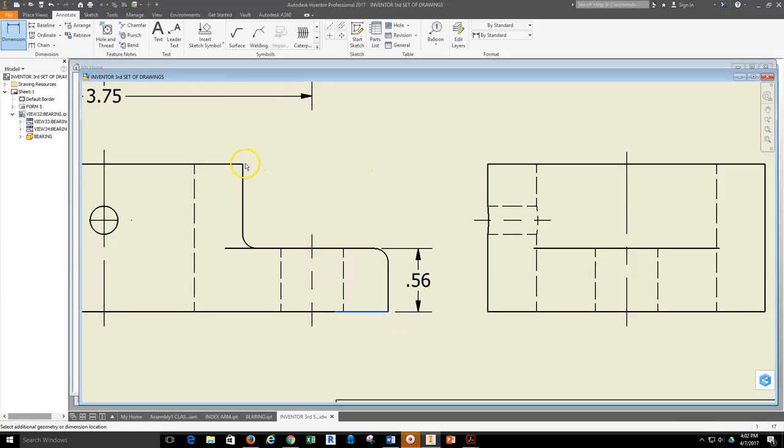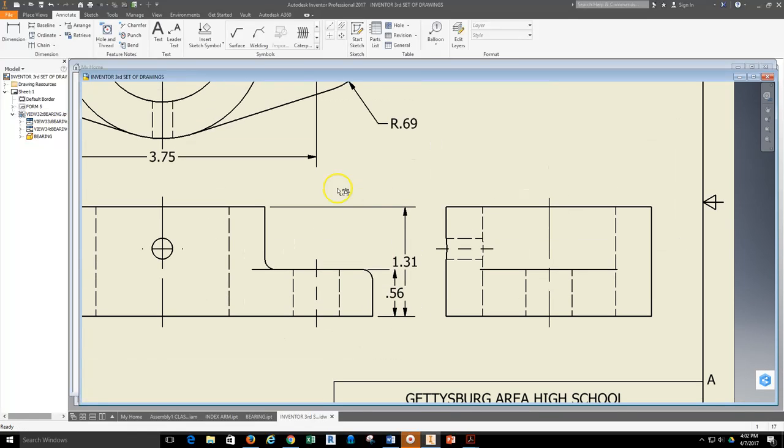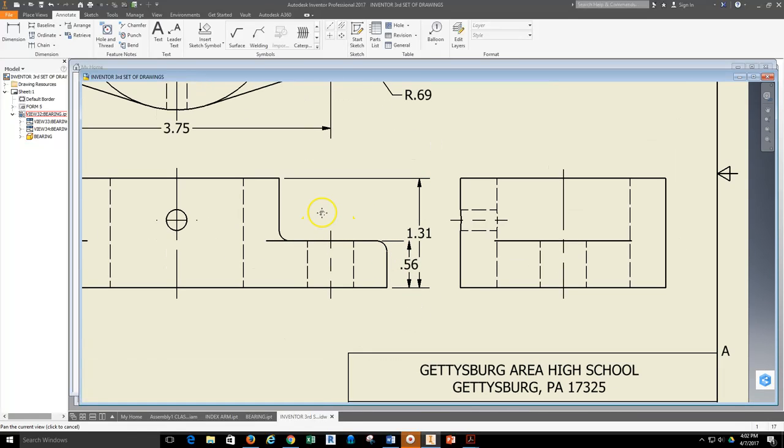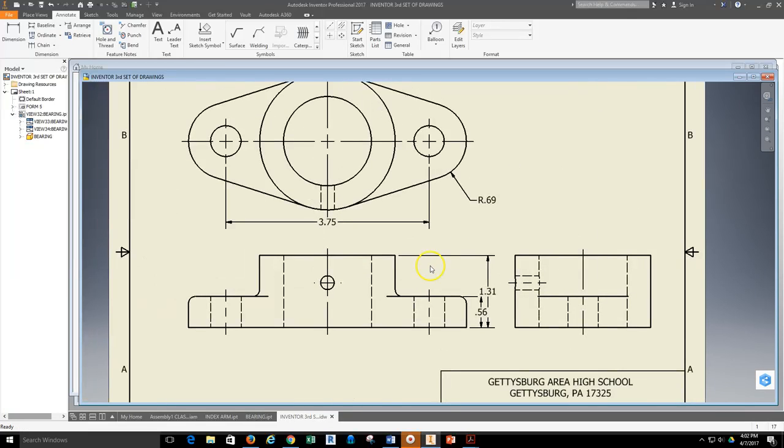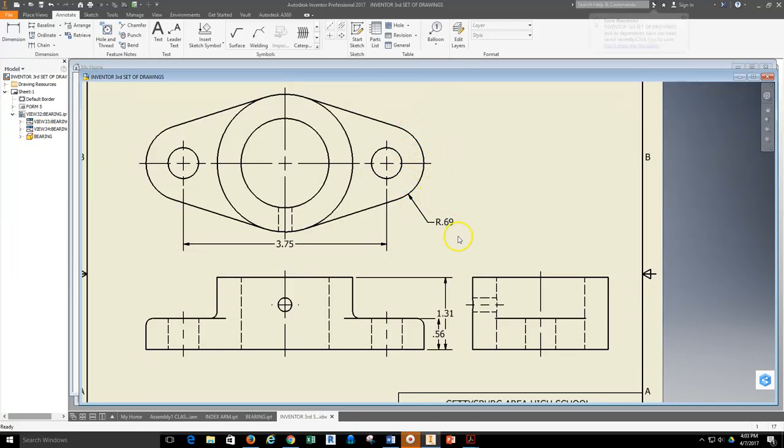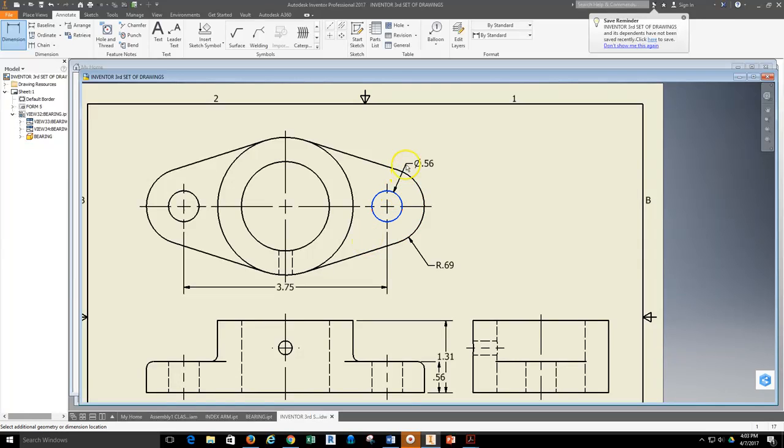And then I'm going to go ahead and create the larger dimension. So I'm going to pull out in this direction, and that's set up now to lock out at 1/4 past the first dimension. So we have that set up, so they're going to lock out there for themselves. Then I'm going to keep moving forward with the dimensions for rounded ends, it's my radius. Then I'm going to set up dimensions for my holes. So go ahead and select, and it's already going to be set up here at the proper diameter, and then I'm going to set up a diameter dimension for the center hole.